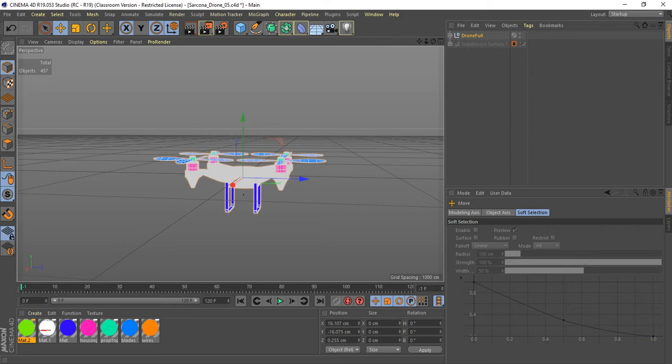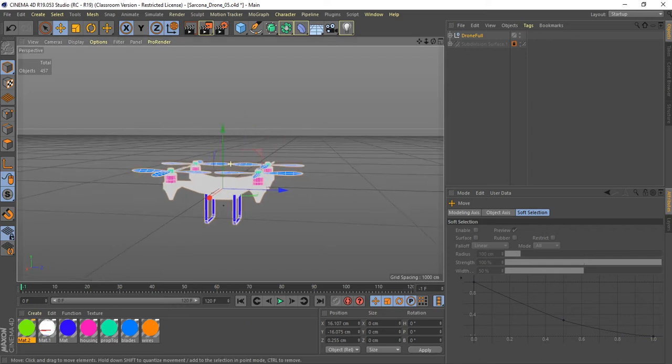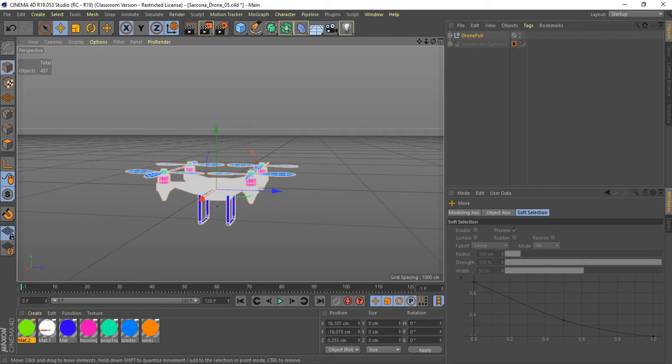We're not animating a camera moving around because KeyShot sucks at animating cameras moving around. So our camera is going to be a still shot, basically a still camera, with the drone moving. So we don't want to have too much movement here. So we're going to imagine the drone is right here. I'm going to go to frame 60. And it doesn't have to be right at 60. You can be at 55. You can be at 62. That's fine. Just roughly around that region, okay?